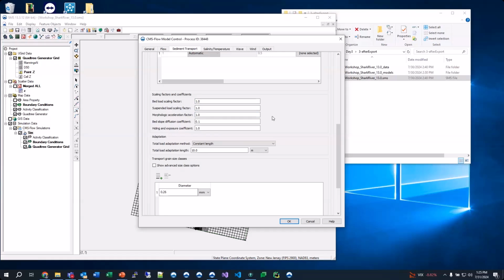We ran a case where we wanted to see if we could run 100 years and what that would do. So we basically ended up getting forcing for 10 years, and then we made this acceleration factor 10 and then did some comparisons. At some point in the future, we might be able to use this morphology acceleration factor a little bit differently. But I would stay away from this if possible and try to tune the model a little bit better for validation with these first two parameters.